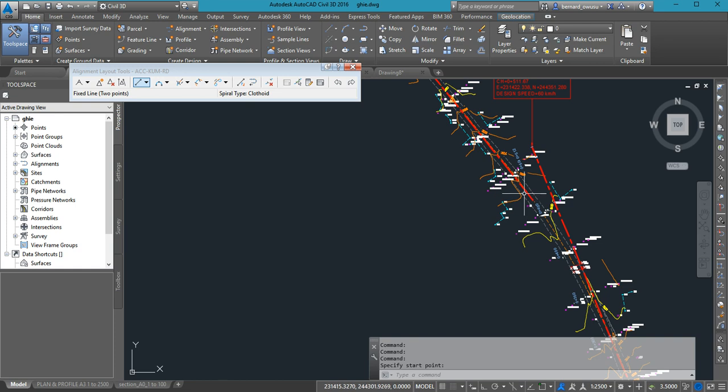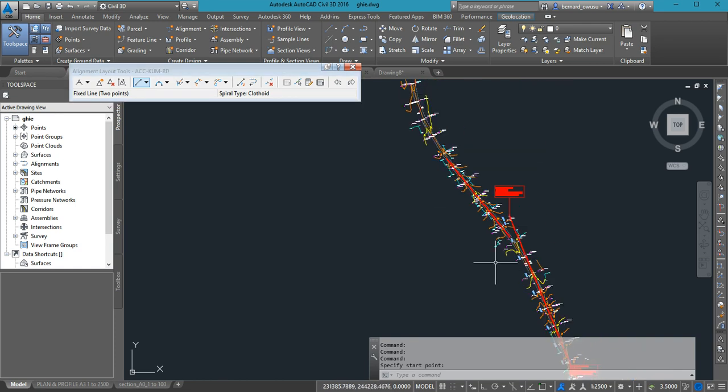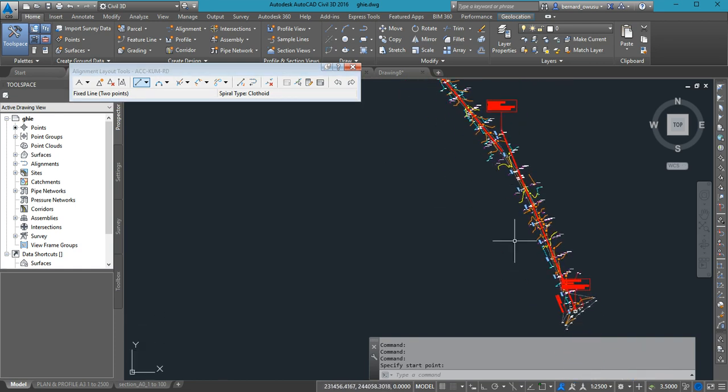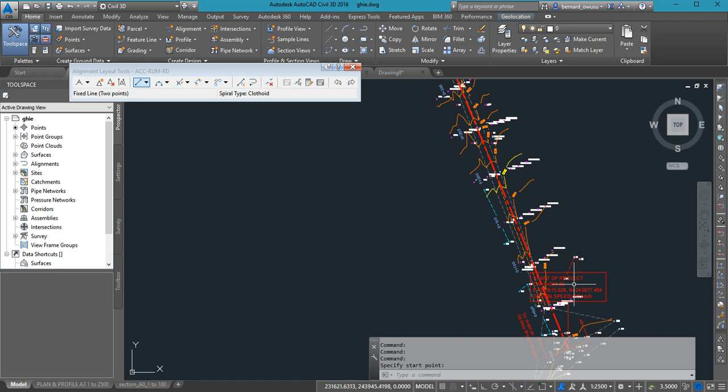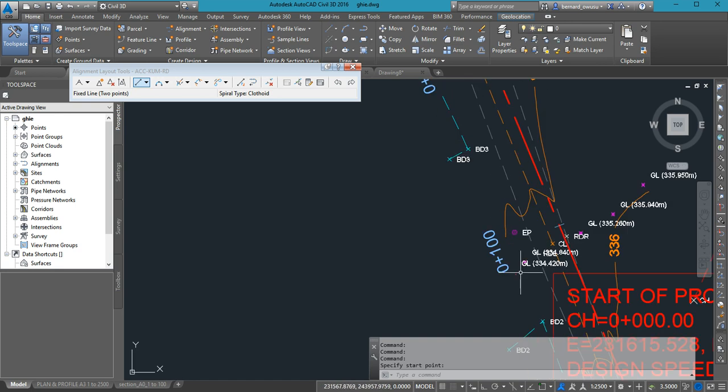Are we okay? Okay. Now, before we do that, you remember when we started, we said we want to have an idea of our road width. We came up with 14.3. So 7.15 to the left, 7.15 to the right. Is that not it? Good. So what we are going to do is define something like a boundary, an offset, running from beginning to the end, so that that will also guide us.